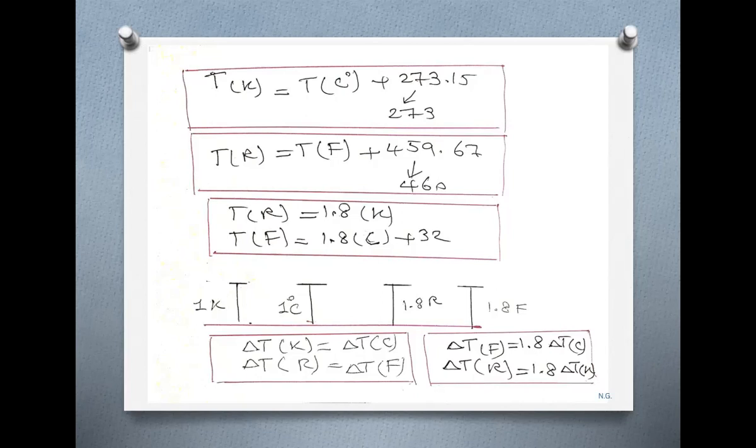And for Fahrenheit, which is in the British gravitational system and English engineering system, if you add 460 to Fahrenheit, that converts it to Rankine, which is absolute temperature in the English system or British system. So that's a conversion you need to know because it's a formula. You have to use the temperature in terms of absolute, like in the ideal gas law. You cannot use Fahrenheit or centigrade, right?